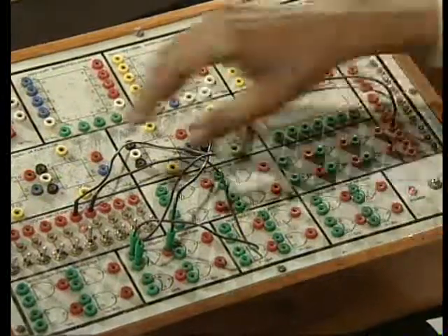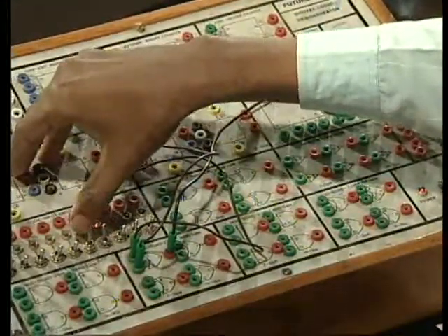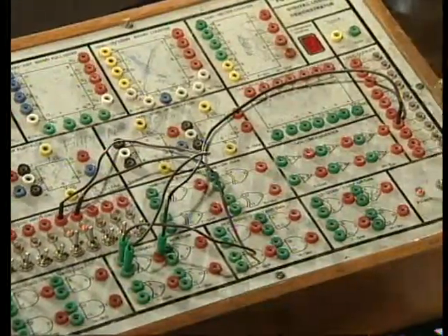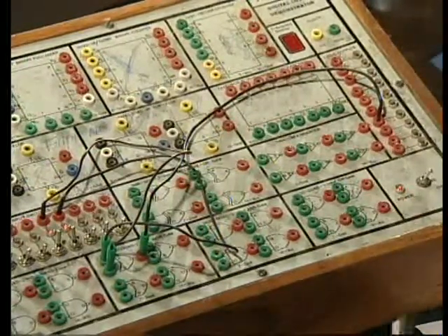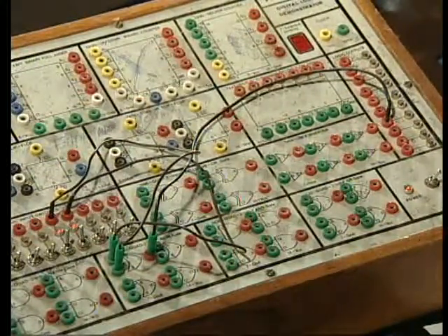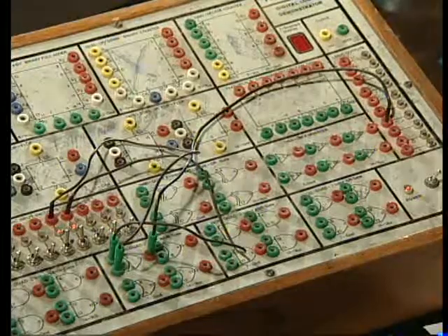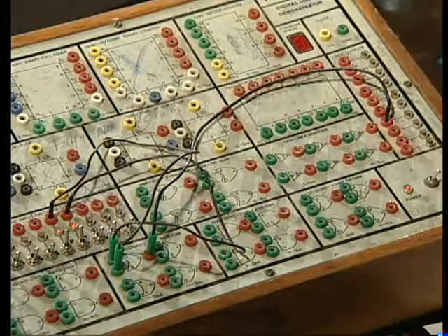When both inputs are high, that is 1 1, the output is still 0. This confirms the truth table of the NOR gate, that is when both inputs are logically 0, only then the output is at logic 1. So, this is the verification of the truth table of NOR gate.